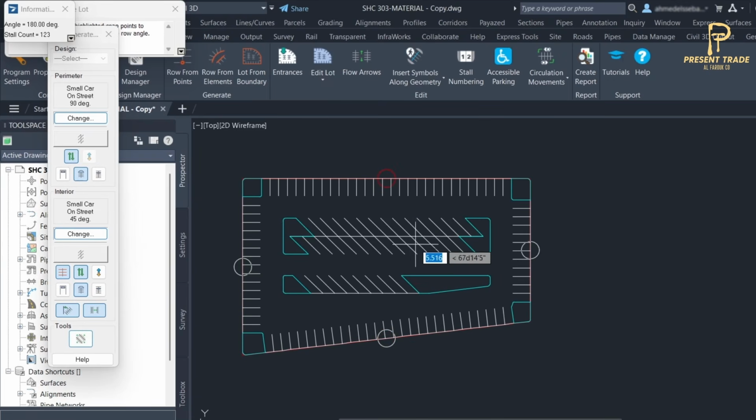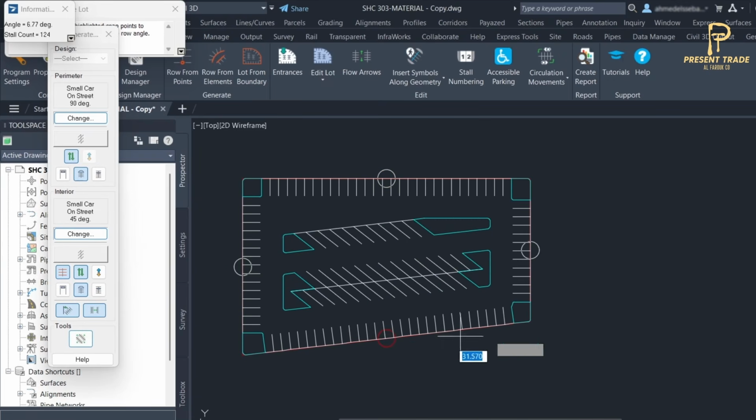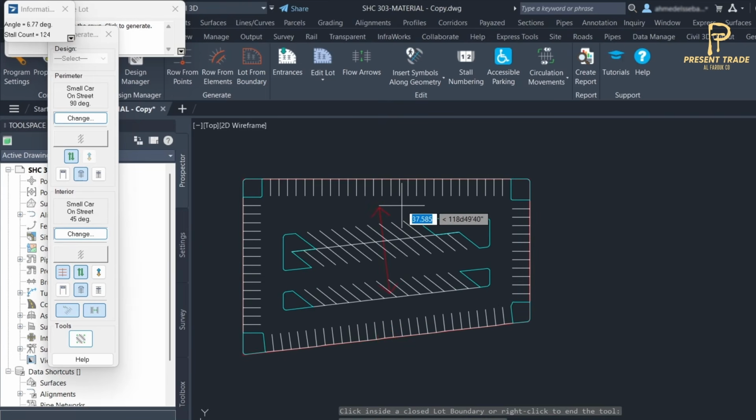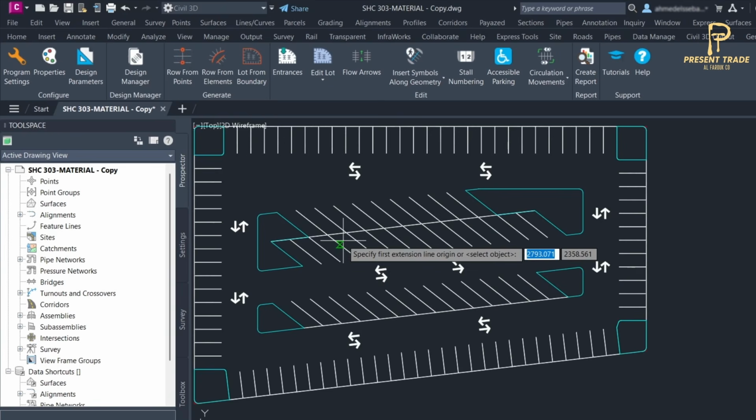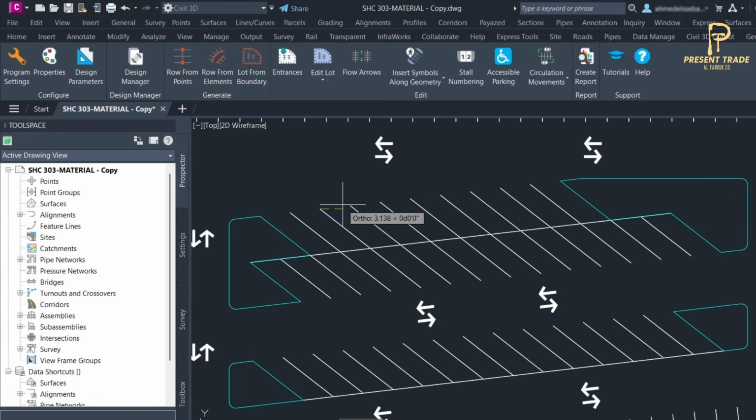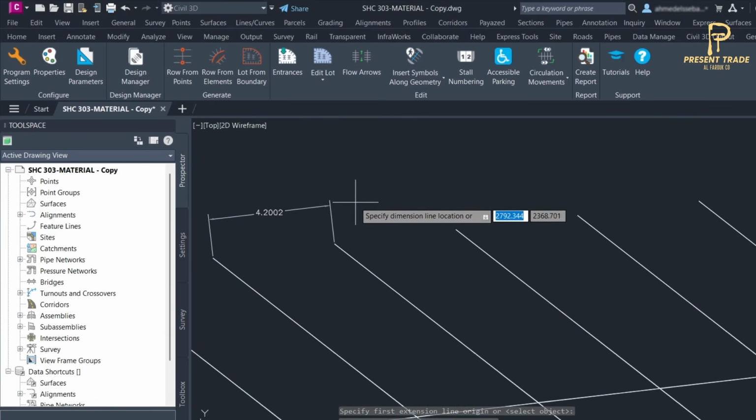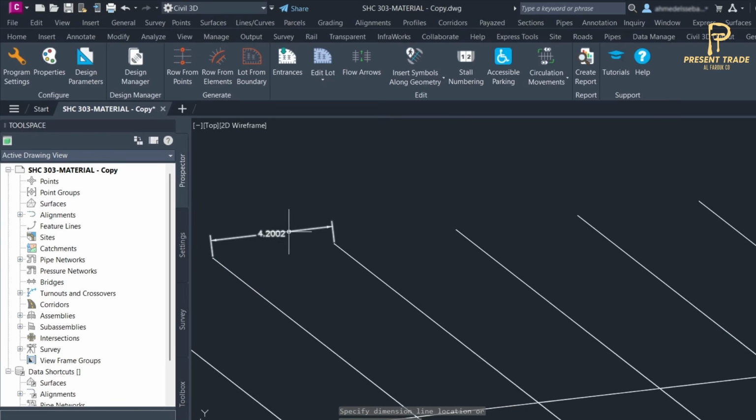And we're done. But let's make sure the design is actually following the values we entered. We'll check the dimensions directly in the drawing. As you can see, the stall width is 4.2 meters, matching the value calculated by our standard. So instead of manually entering these requirements every time, we now have our Saudi parking standard saved directly inside ParkCAD and ready to use whenever we need it.